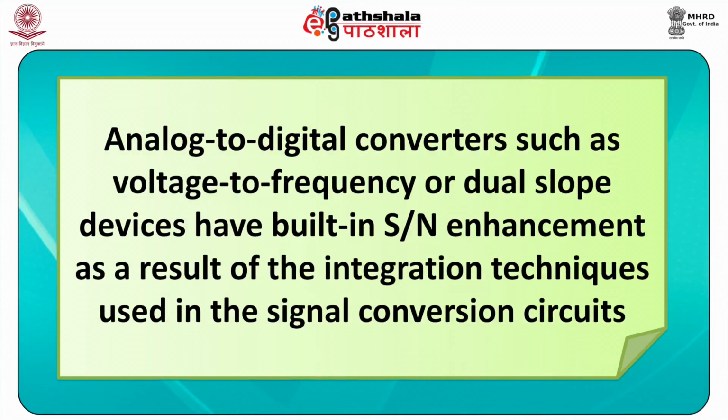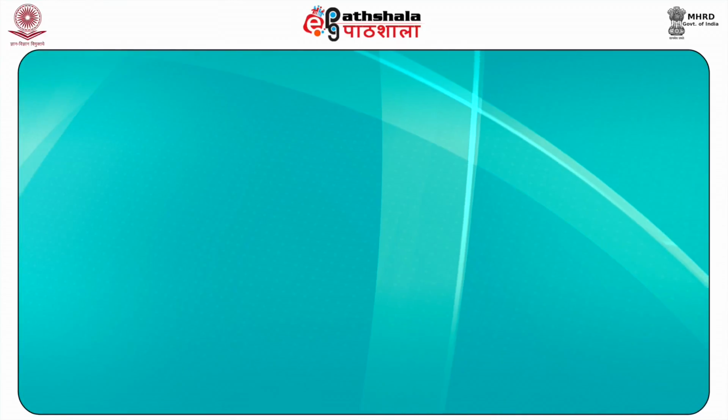Analog to digital converters such as voltage to frequency or dual slope devices have built-in S/N enhancement as a result of the integration techniques used in the signal conversion circuits.